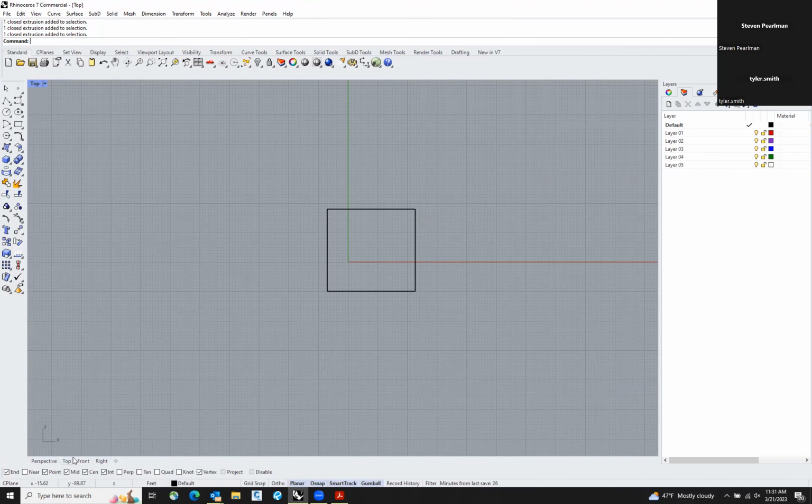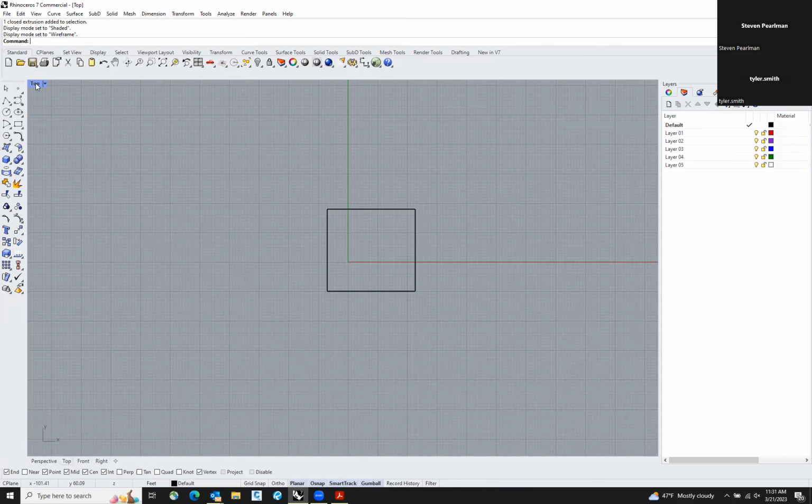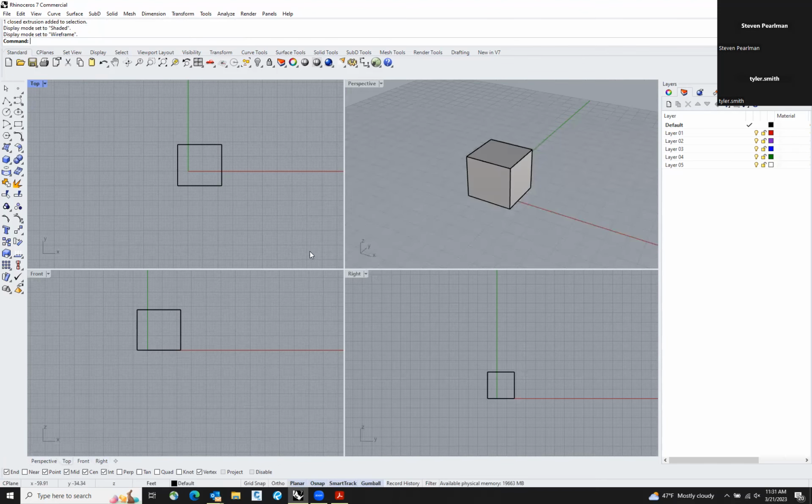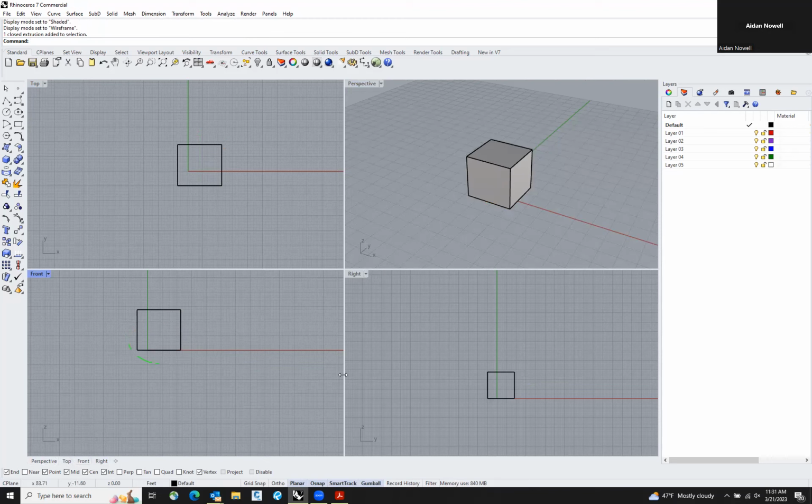Also to note, in these 2D views, you can set different display options as well. And if you double click, it will take you back to the 4 window view frame, which is nice because it allows you to see things in the front, top. So as you're modeling, you can utilize all of these windows to aid you in your 3D modeling.